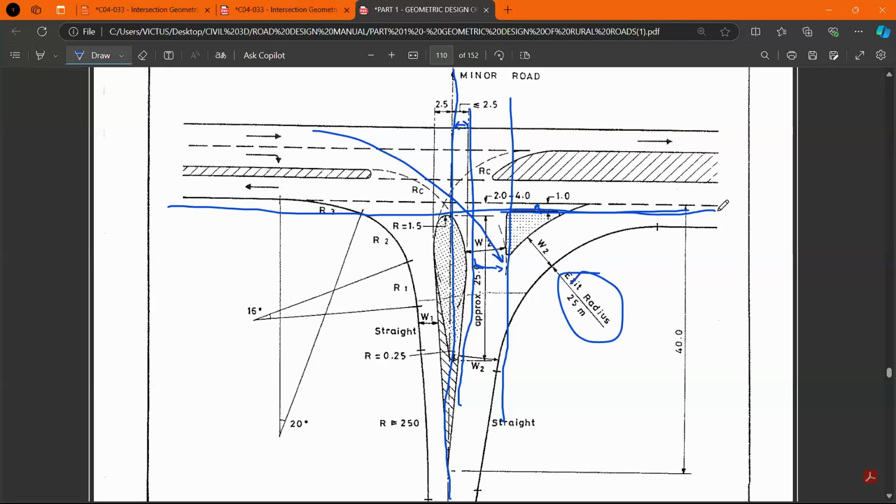And that is where you will do a little bit of widening here, and then boom, it forms itself. So what you need to do now is offset this again by 3 meters, and it will form this arc at this point. So all you need to do now is to trim these edges, and the ghost island will form itself without you necessarily having to do the specifications for that area.